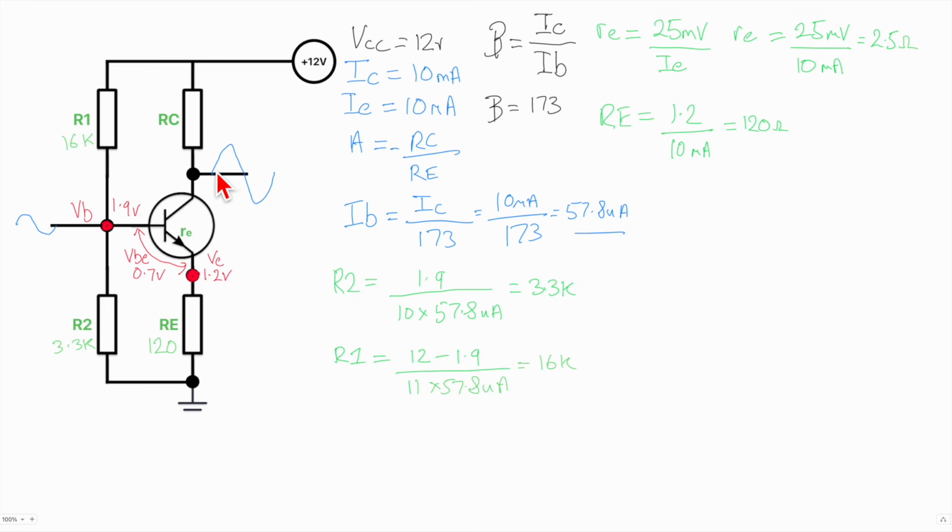And if we don't get this point right, if this zero crossing line is too high, there won't be enough headroom for our waveform and it will be clipped. And the same if it's too low, it'll clip the bottom of the waveform. And clipping, of course, will mean distortion. And in an audio amplifier, as this one is, you'll hear that distortion. But in any kind of Class A amplifier, you don't want to do that.